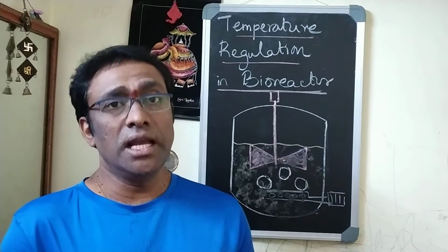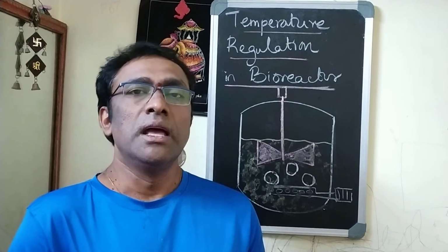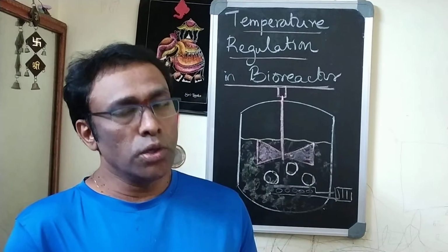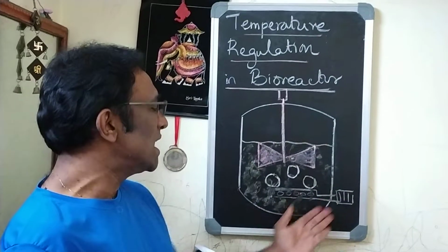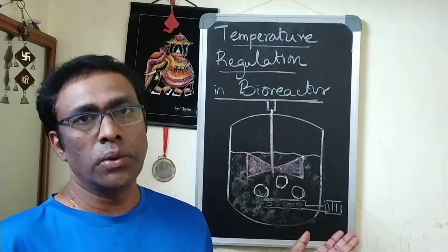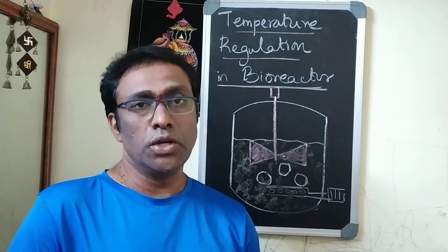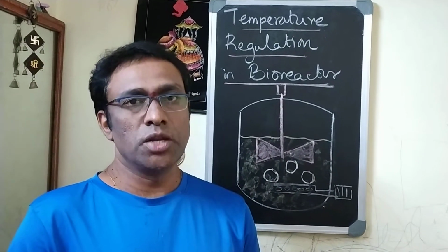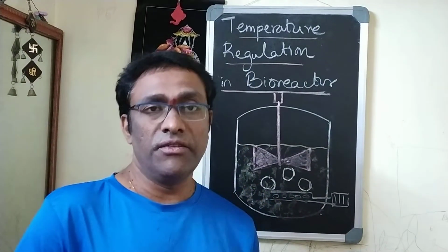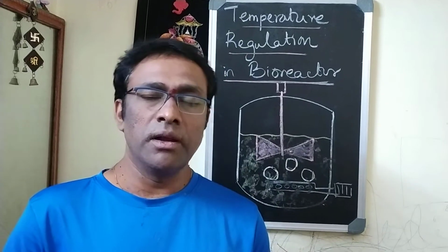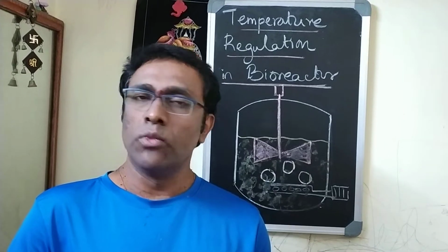So we understand every cell undergoes the mechanism of catabolism and gives energy, but the energy is not only for its functions, it is also lost as heat. Thus in a bioreactor we can expect thousands of millions of microbes growing, and they all are going to generate heat. Imagine what's going to happen if temperature increases in the fermentation process. The cells present in the inoculum will be affected, the product will be affected, right? So for better enhancement of the product, one should monitor the temperature.